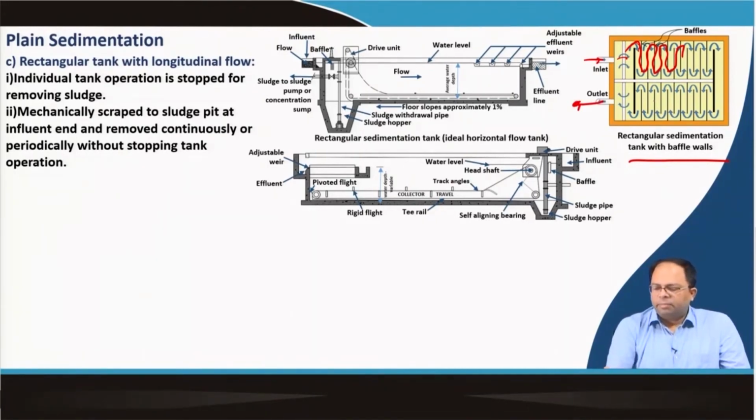There are several baffles which are created, and that makes the water flow in a particular order. The detention time of the water is determined by the speed of the water through these baffles, and during this entire process, sedimentation happens continuously. So, rectangular tanks with longitudinal flow.